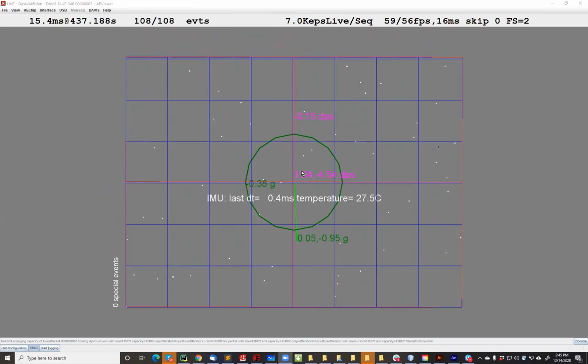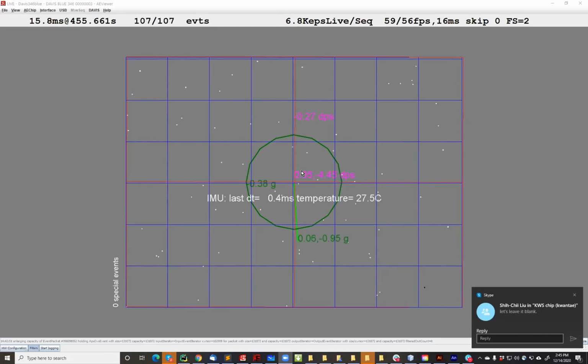Does that make sense? Yes. So we take the XY addresses, we rotate it with this 2x2 rotation matrix, and then we add the translation, which is a vector of XY translation, and that compensates it. And just do that on each event as it comes out of the camera. And you can do that down at sub-millisecond timing resolution.